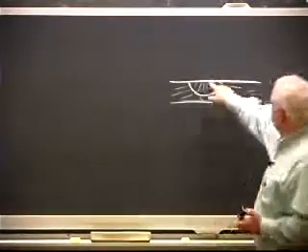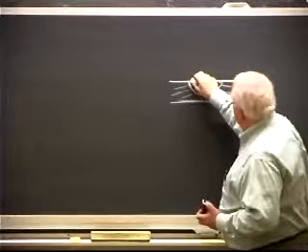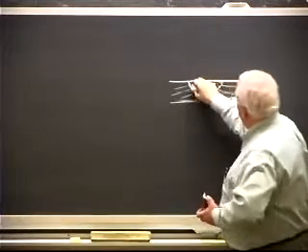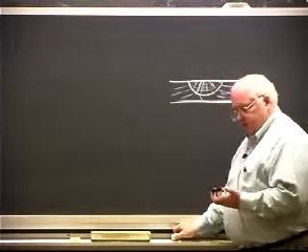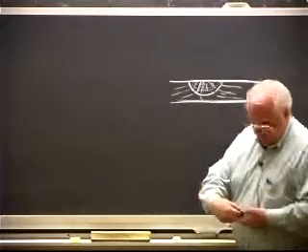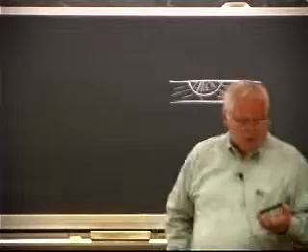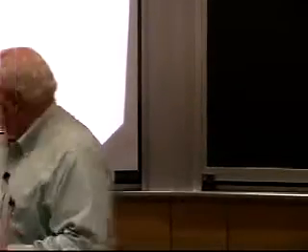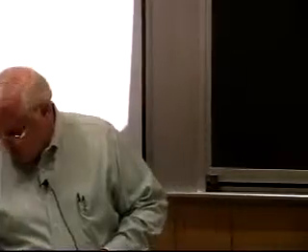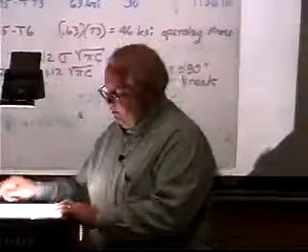Actually, this is the fatigue crack, okay? You can't see, but if I went into an electron microscope, I could find the beach marks there, but you'll see kind of this little thumbnail shaped region if you get it at the right angle of the light. It's about the size of a thumbnail, and it goes about 80% of the way through the thickness of this thing, okay? So that was the problem. I said, oh, well, it's a fatigue crack. This thing's messed up at the bottom anyway. Well, I'll have to redo this some other time.